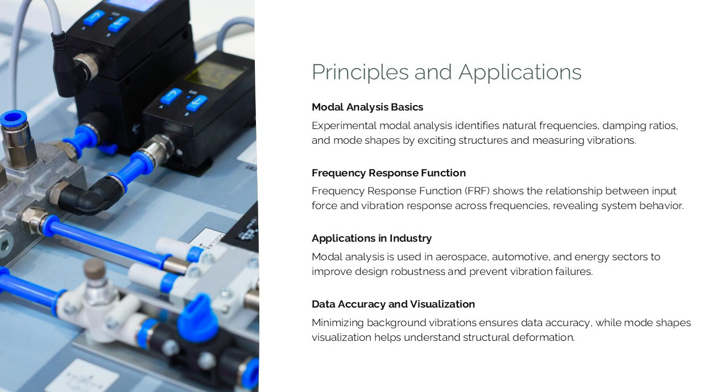The ratio of vibration response to input force across frequencies forms the frequency response function, FRF, which provides critical insights into the system's behavior. Modal analysis is invaluable for validating finite element models, identifying resonance issues, and improving design robustness. Accurate data collection requires minimizing background vibrations during testing to avoid interference.